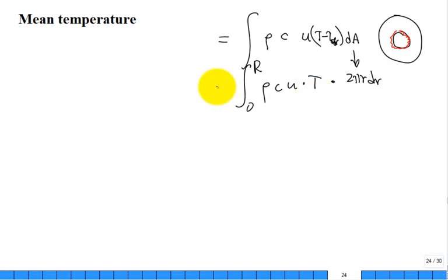All right. What about over here? Well, I have the same mass flow rate times specific heat times the temperature, and I'm really interested in the mean temperature. This gives me the equation for the mean temperature. That mass flow rate would be rho U_m A. Isn't that the mass flow rate? And so the mean temperature equation is,